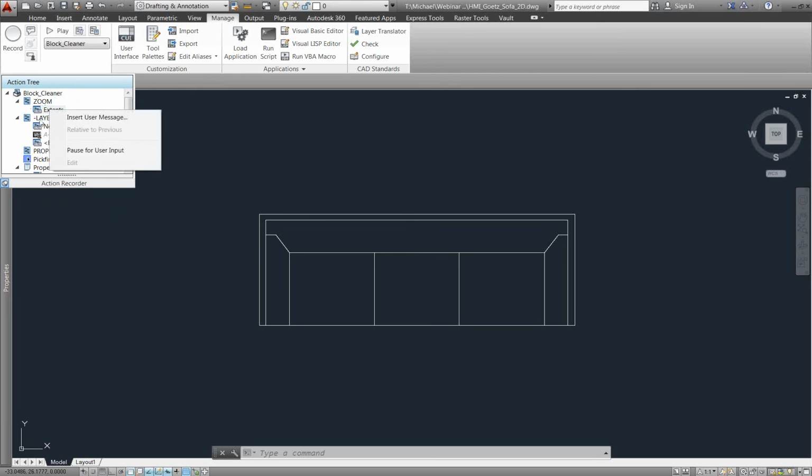You can also, depending on the action you select, when you right-click, choose if user input should be specified. This allows you to specify maybe a length, a radius, something like that. Change the property when it prompts you for something, change what actually gets placed.